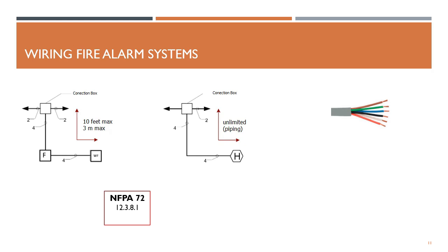What is shown is the pipe, but inside the pipe, as you can see, we have 4 strands of cable, as we have the outgoing cable and the return cable in the same pipe. This is allowed by the code, but we must comply with the rules.